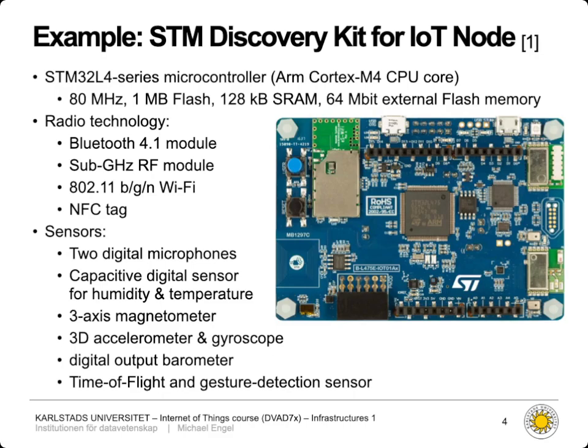In addition to all these components, you see there's some pin headers at the edges, so you can connect standard I/O modules to extend the functionality even further. So you have 2 rows of headers which are compatible with the Arduino AVR boards, and the header on the left lower hand side is a so-called PMOD header. This is a standard which is very common in FPGA applications usually, and there are a large number of PMOD compatible modules available on the market for very many different use cases.